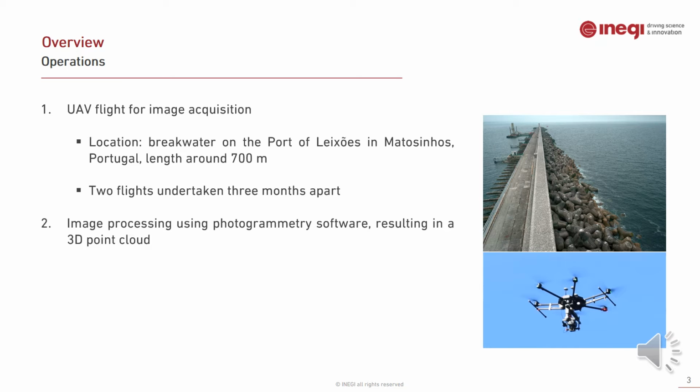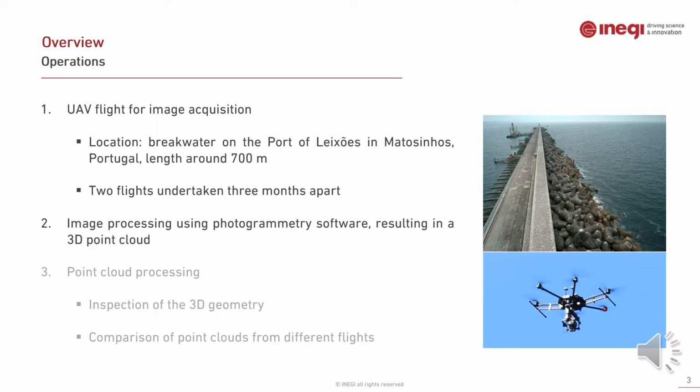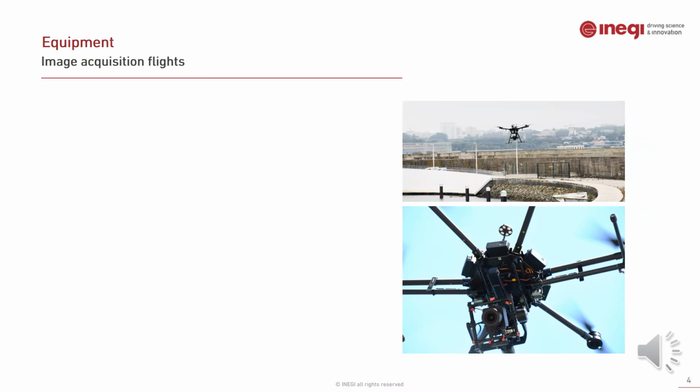Then the images obtained were processed using photogrammetry software, resulting in 3D point clouds. And finally, we took meaningful results from the point clouds, being able to inspect the 3D geometry of the breakwater for any single one of the flights, and compare the point clouds from both flights.